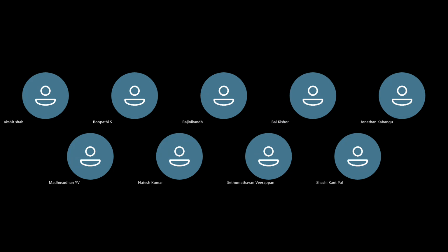Under the component selection, as I told you, resistors, capacitors, diodes, and even connectors are very important. That's the reason I have included connectors this time. And we have relays, because many of you are power electronics guys. Even if you are not, try to use low power inductors, maybe low power relays with 2 ampere ratings or something like that, because these are used in many signal switching applications.